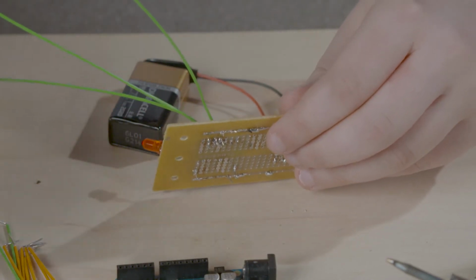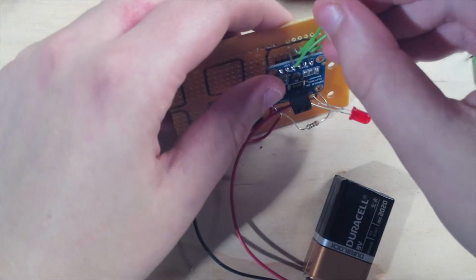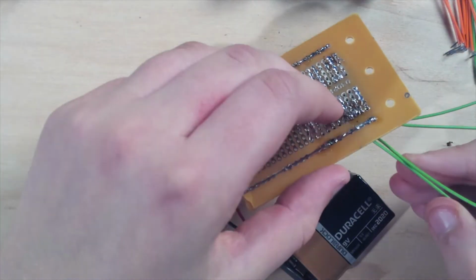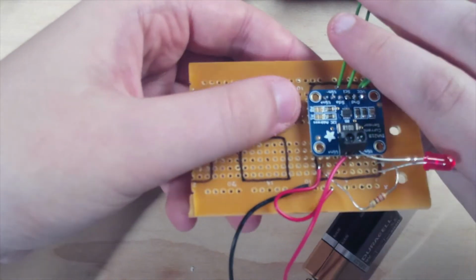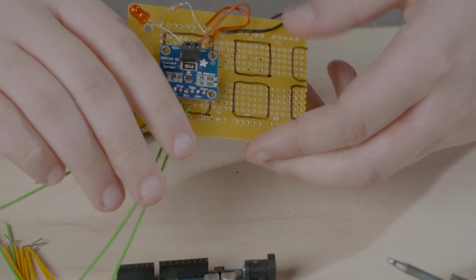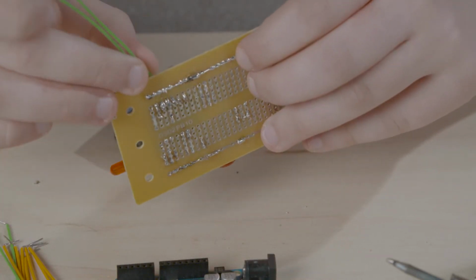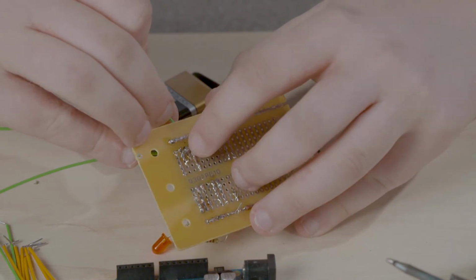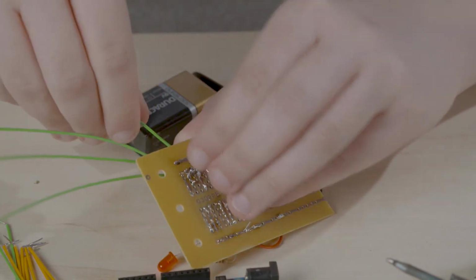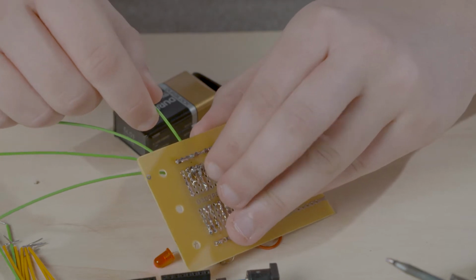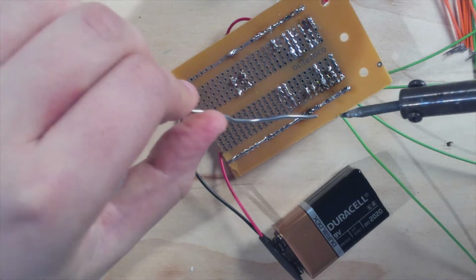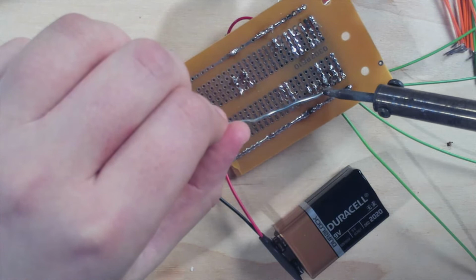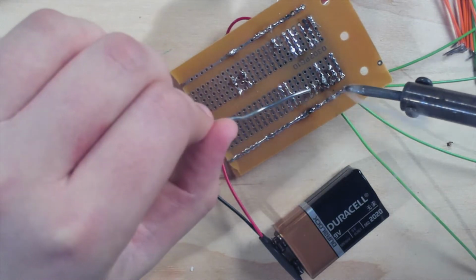And we'll add the last wire for the current sensor, for the SDA pin. You should flip it so they can see the front. Right there. It should look like this. Okay. The hardest thing when doing this is that you have to make sure that only the correct pins should be touching. Otherwise, it would not work. Only the ones on the same row.